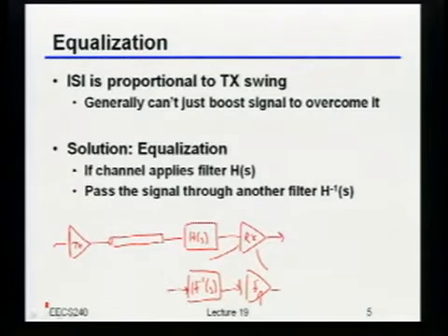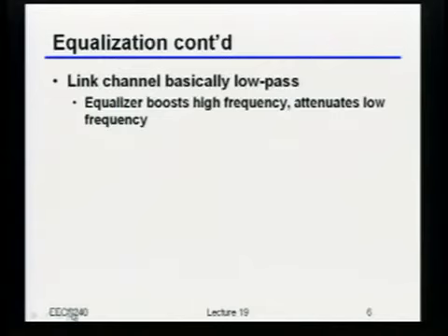So by the way, this is called an equalizer because this is kind of like saying that if this introduces some frequency selectivity, meaning some different gains at different frequencies, what this thing is doing is the opposite of those gains, so that the response over all frequencies becomes the same. Okay? So very simple concept, but we'll see it's actually fairly interesting to build. So let's think about what this would imply in our context.